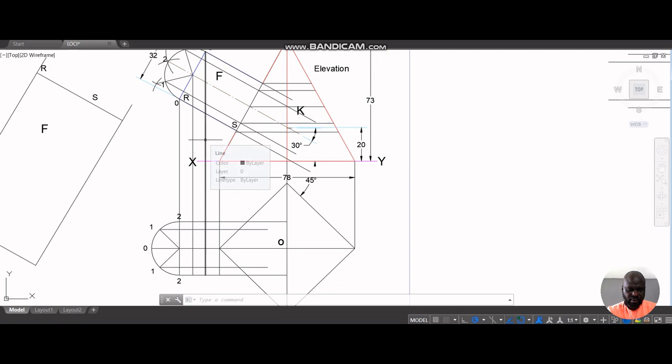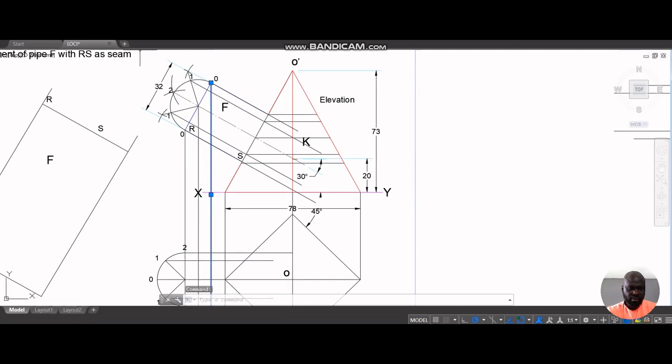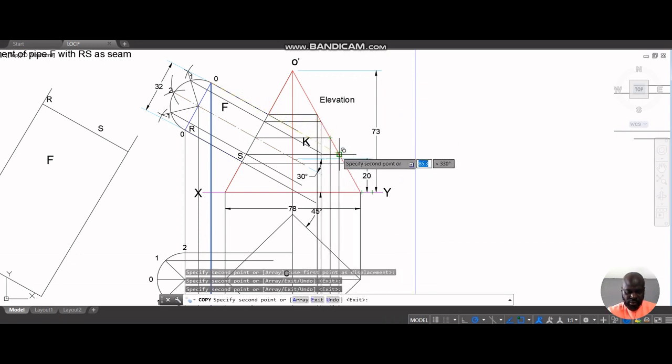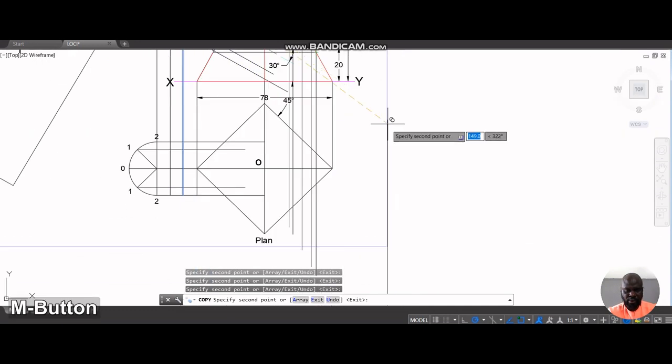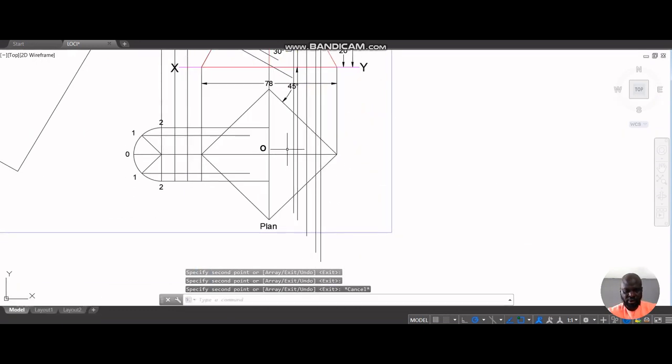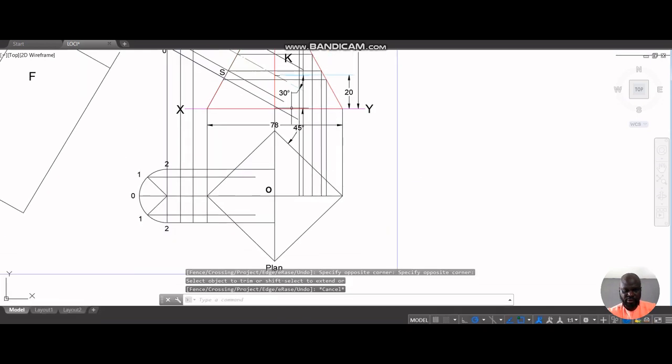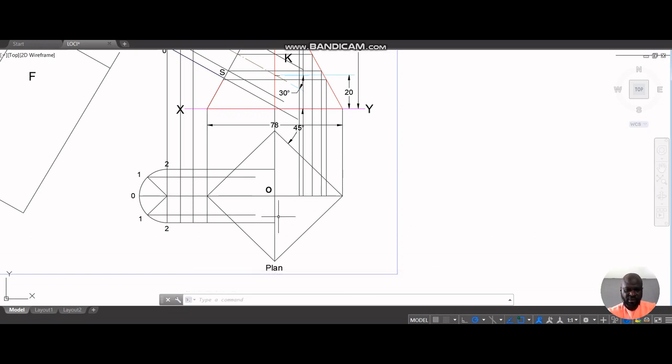I do not have to draw construction lines anymore. I can copy one of these construction lines and just drag them home. Here, here, here, here. Those points on the line. But I'll terminate them on one known reference point, which is the horizontal line, because they pass through this XY plane. So we're terminating them here and redirecting this point at 45 degrees or parallel to the edges of the plane. This edge of the plane has to be represented all around here.